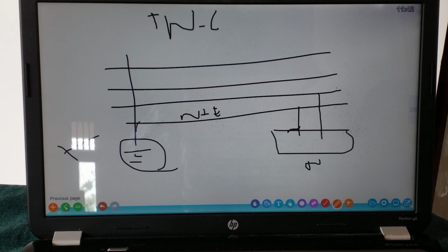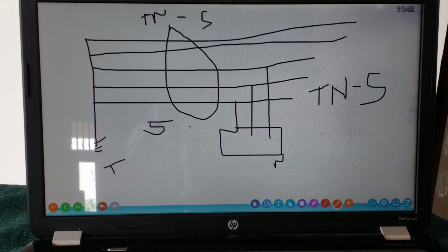What is the problem with T and S? We have to have 5 conductors, one more conductor. It causes severe headache to line designers and also the construction party. Previously it was 4 conductors, now it is 5. The weight, bearing capacities, all the things of the poles have to change. Everything, bobbins, all the things have to change. It's really headache and a very costly solution.